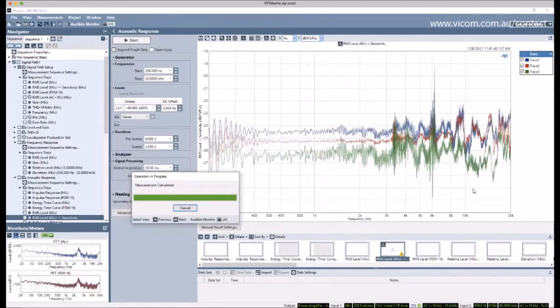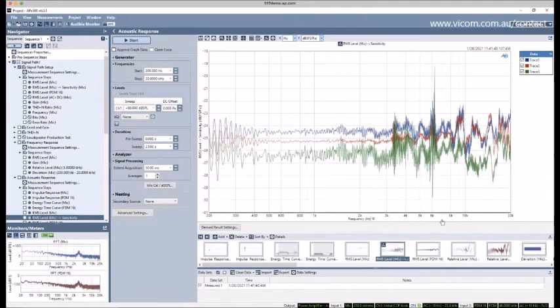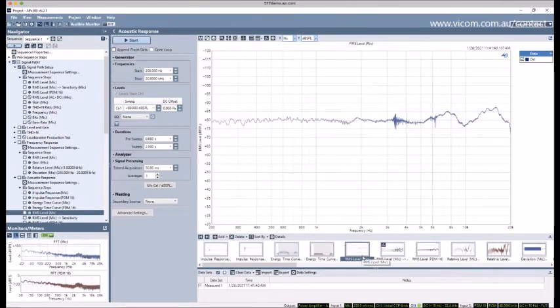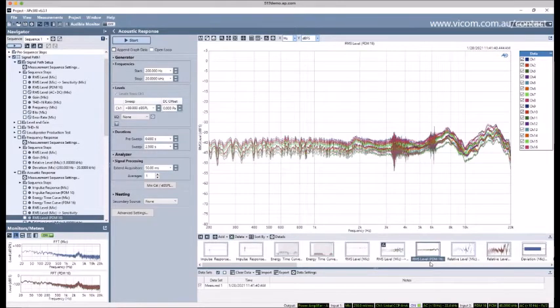And again, the frequency responses, there are still odd little things here that happen because of the behavior of the speaker, but the frequency responses, again, basically come out the same. And that's, again, because by calculating this as a ratio between our reference microphone and our PDM microphones, we are removing or dividing out the source speaker.